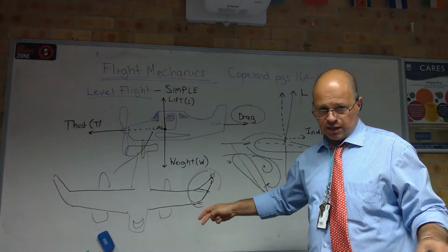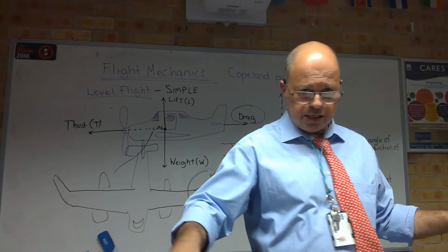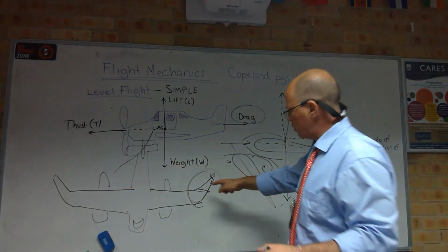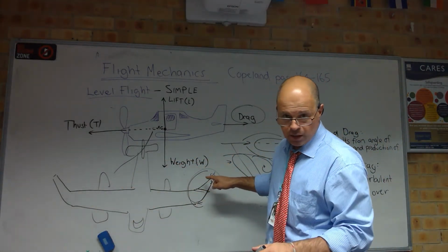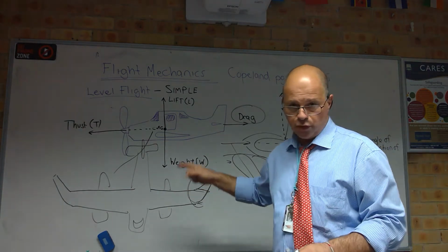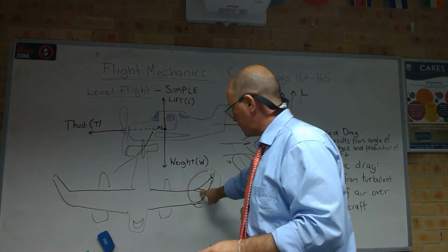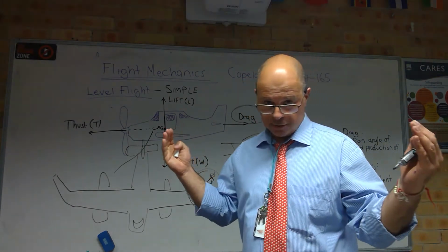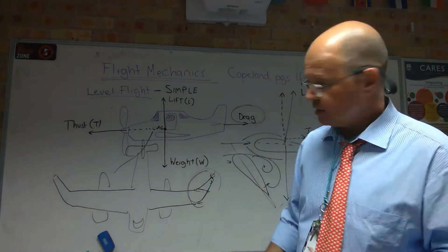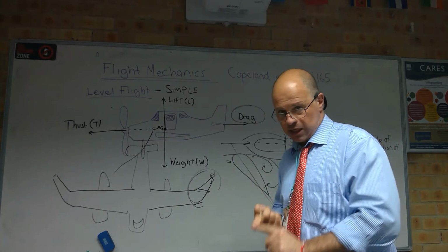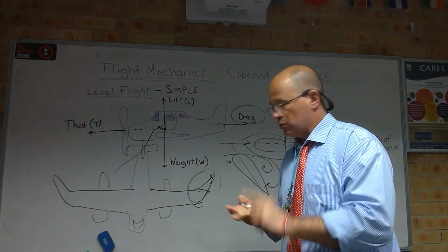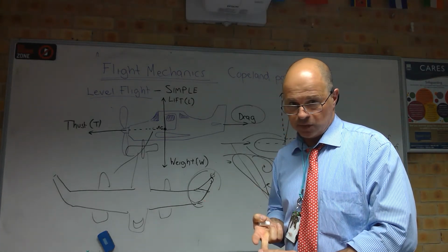Both of these designs have been seen in nature; you'll see a lot of seabirds that have this shape of wing, and it's a very effective thing for the cruise. So long haul jet airliners will tend to have a swept back design rather than a winglet, okay? But both are put in place to reduce the wingtip vortex and to reduce parasitic drag, okay?